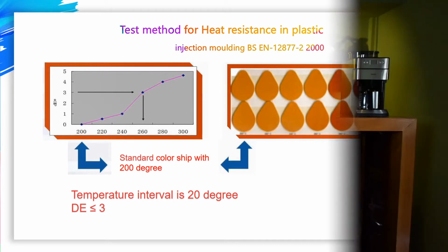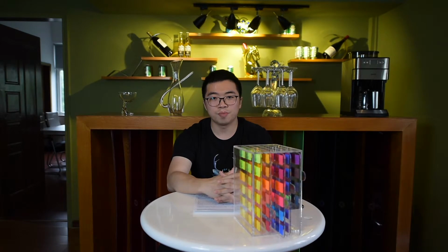At present, the heat resistance index provided by many colorant suppliers refers to 1/3 standard concentration, which is not equal to the heat resistance of the colorants at all concentrations. It is well known that the heat resistance of colorants declines with the decrease in dosage. We need to pay attention to the heat resistance index in color matching for plastic.